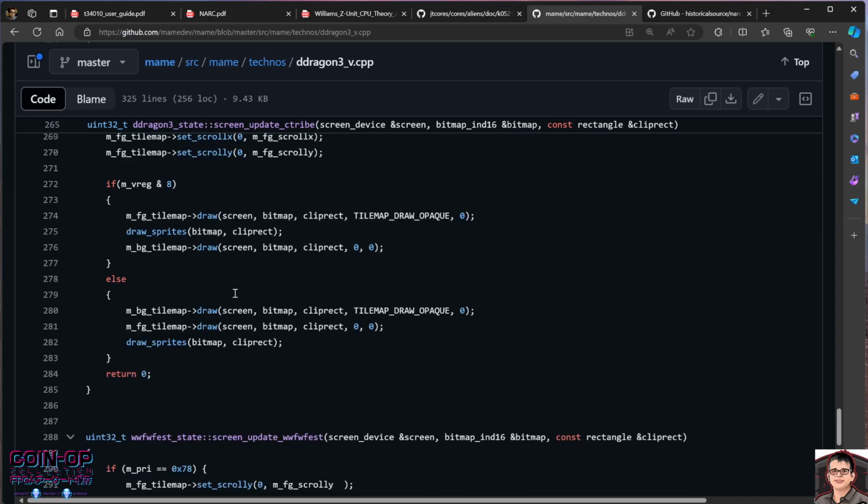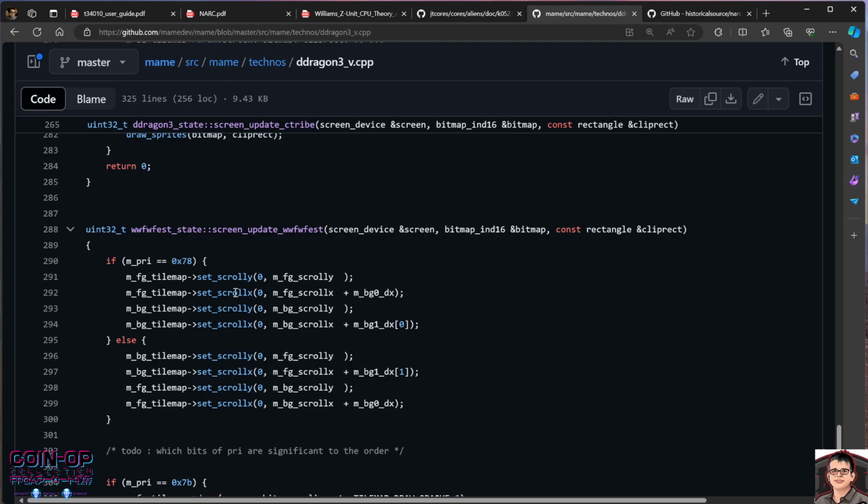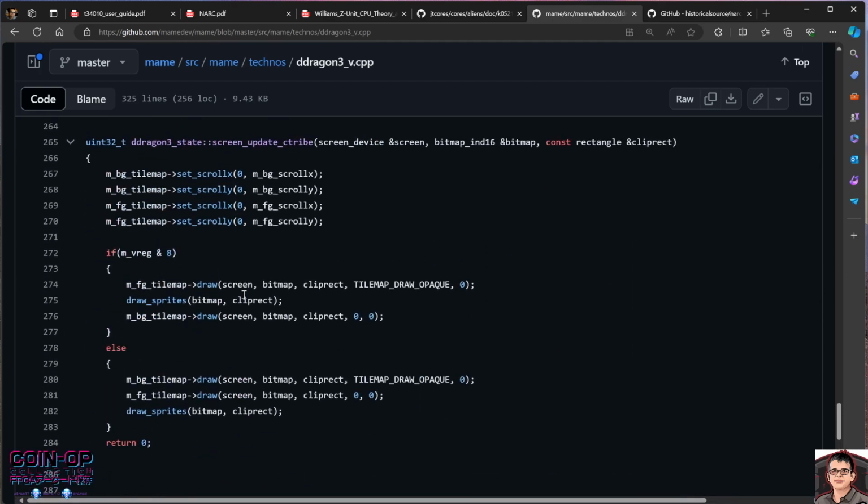And so if you were copying this from MAME, it really wouldn't work, right? Because that's not how the line counters work. That's not even how graphics are drawn in a lot of the boards of the past. What MAME does is draw things on a tile by tile basis, right? So there's a tile map engine, and it draws things tile by tile.